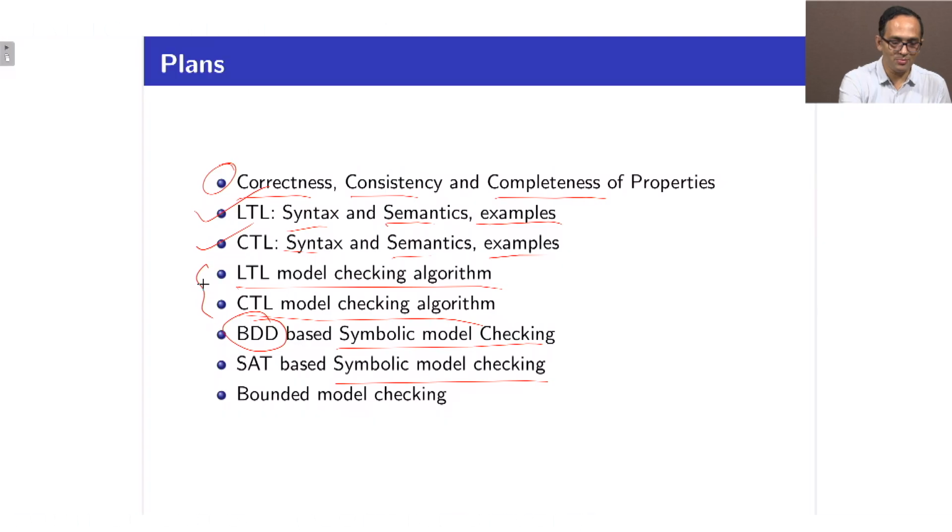I have already talked about binary decision diagrams. So, instead of modeling my state transition system as an FSM, I will model it as a BDD. Then how this model checking algorithm can be done on a BDD is the interesting thing. So, all the LTL and CTL property checking we will learn, we will see how we can do the same thing with BDD.